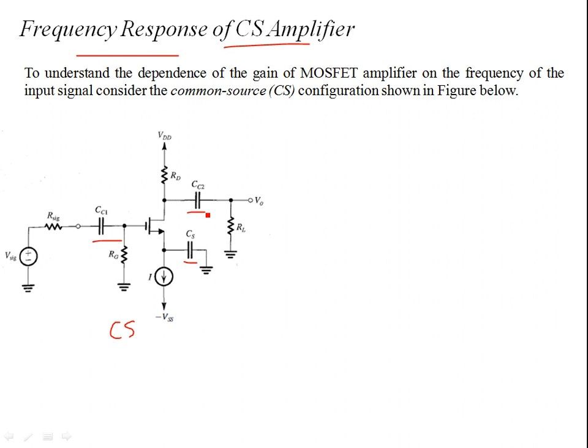But besides those, we have the internal capacitances of the transistor as well, which are in the order of picofarads, or the junction capacitances and capacitances between the gate and the channel, gate, drain, etc. So up until now, if you recall, if you draw the AC equivalent circuit, it was something like this. Without the capacitances, we have the signal source, V signal.